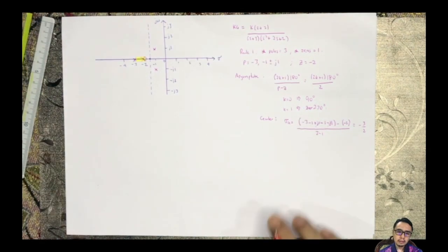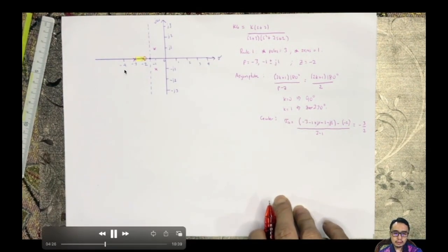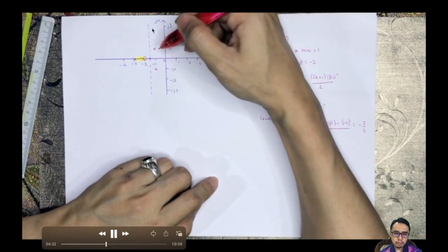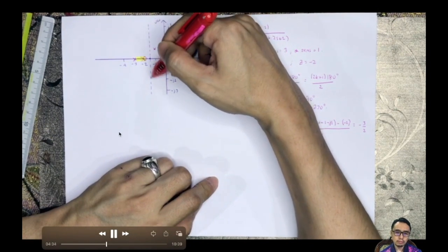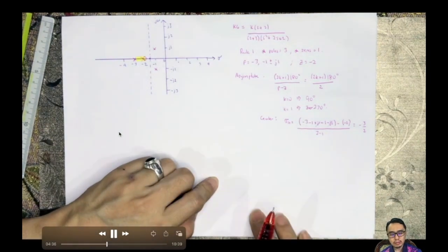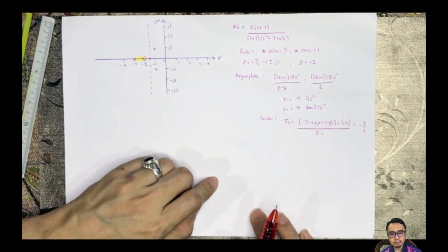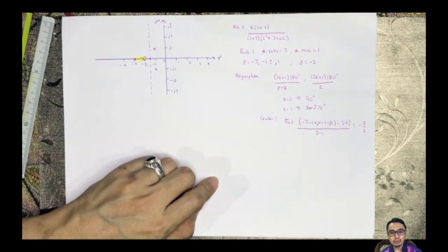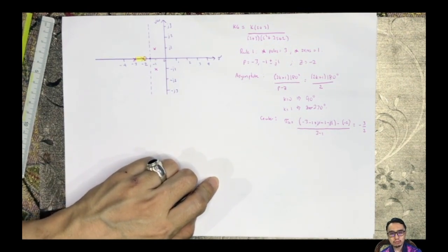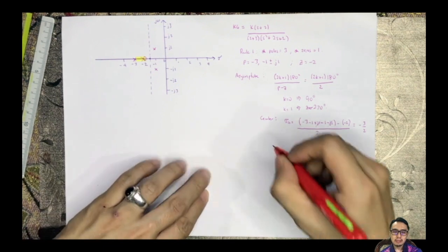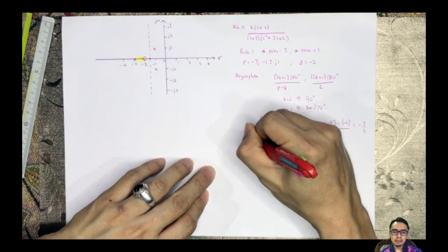Right? So now you know that these two poles will approach these two asymptotes as k approaches infinity. But at what angle will the locus leave the pole? That's where we use the new rule. So we have to draw the vectors made by the others.